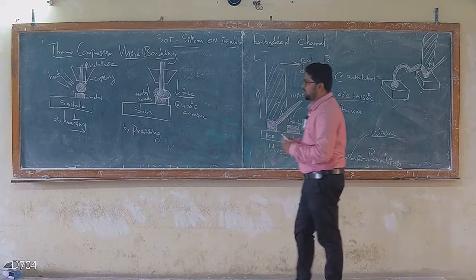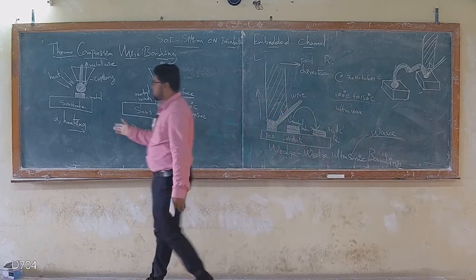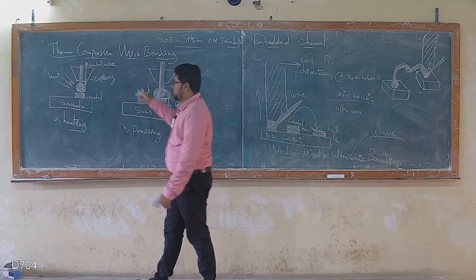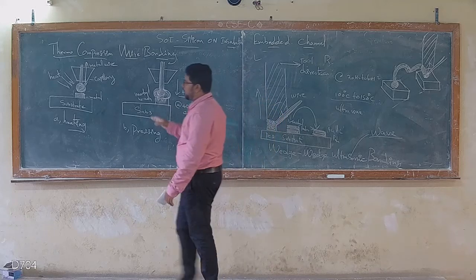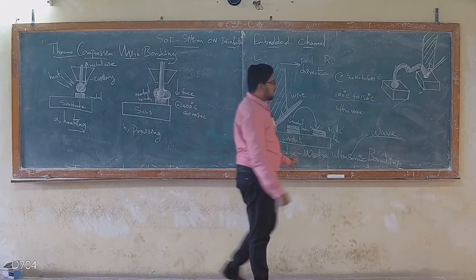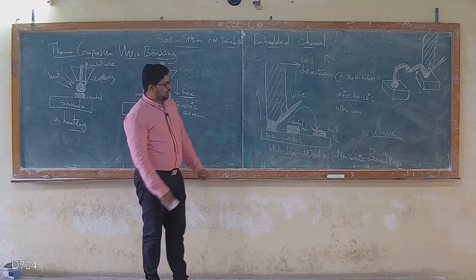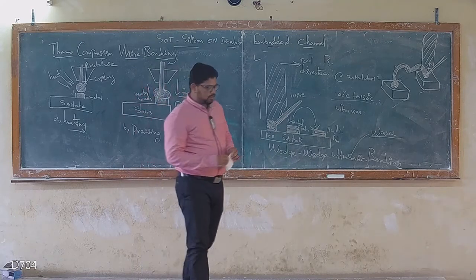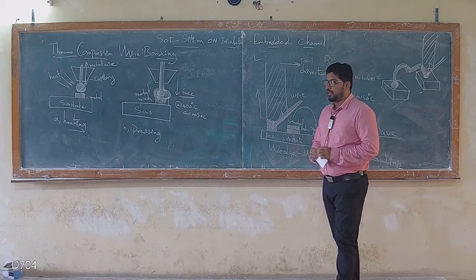The third one is called thermocompression wire bonding. You understand, because of the heat, I could call it thermo. Because of the pressing, I call it compression, and because of the wire melting over the metal contact, I could call it thermocompression wire bonding. The last one is wedge ultrasonic bonding. This is not only by means of mechanical force, this happens because of pure ultrasonic waves. So this will end up with the energy bonding of the thing.